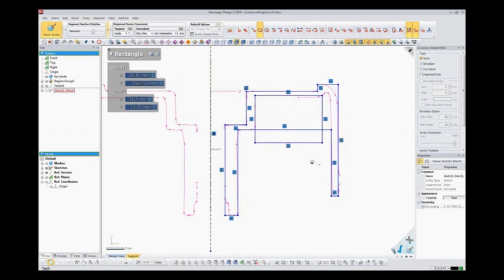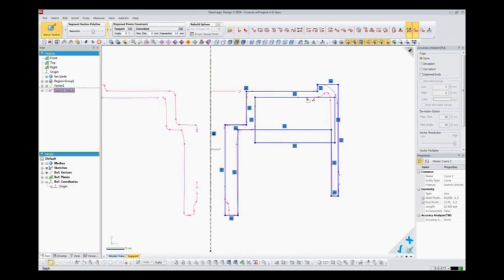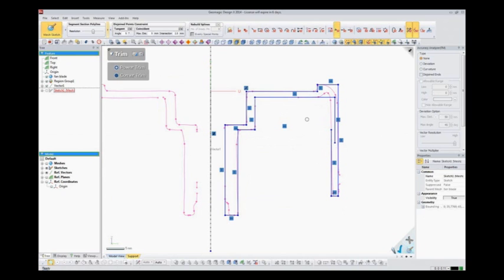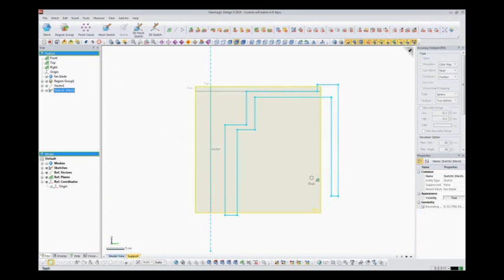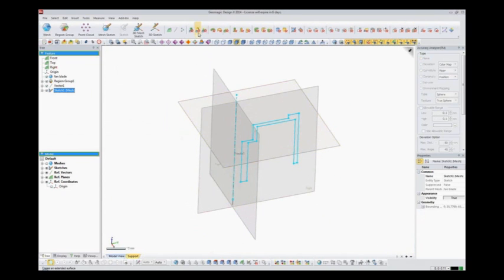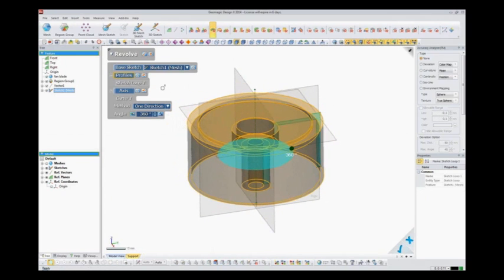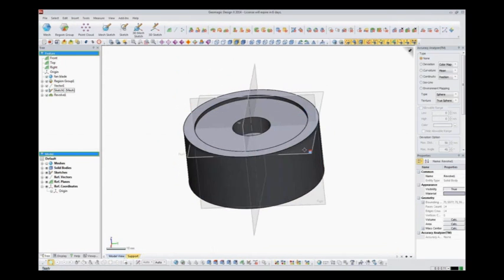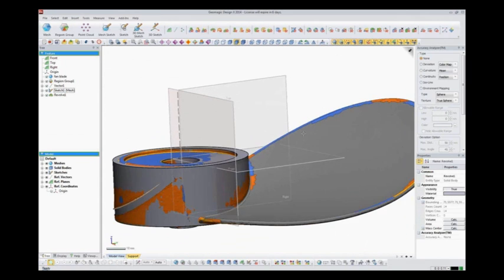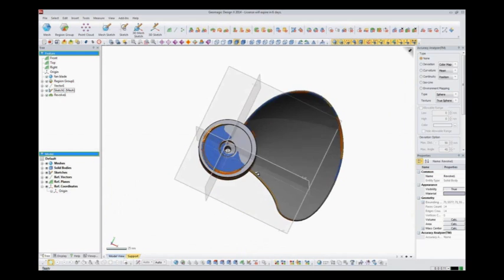And we can have another box like this. Snap it here again. I'll trim away this one and get the corner trim from there to there. So that's basically quite a fast reconstruction of this center area. We care about details later. And now I can just create the revolution body. So this is my hub now. Now I have a base for this fan.